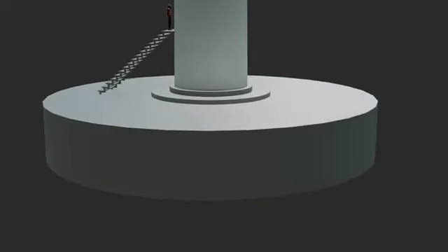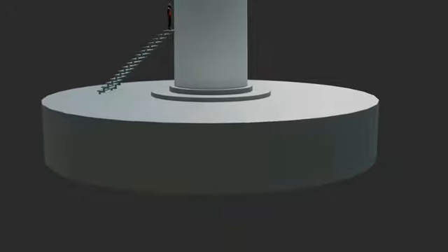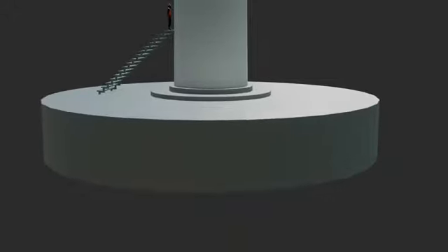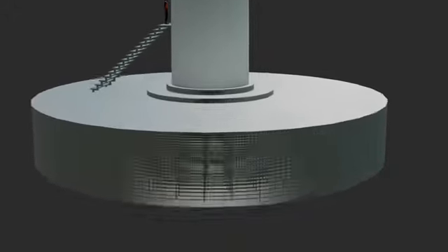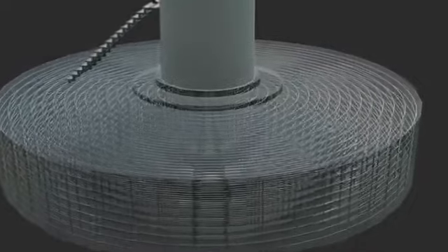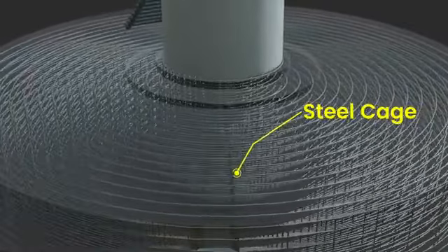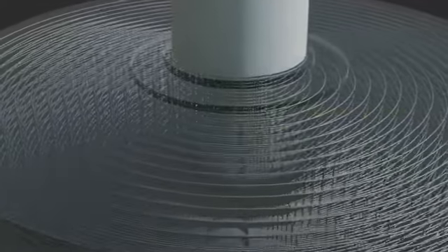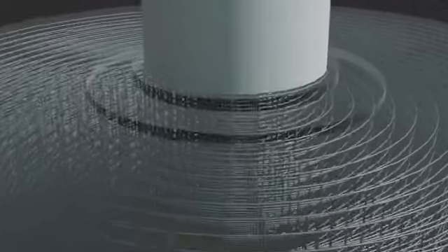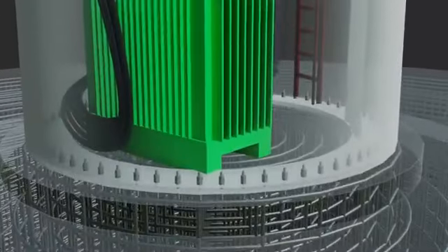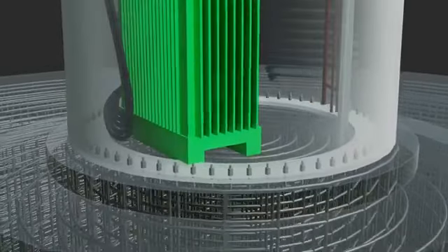A typical gravity foundation for a 2-megawatt wind turbine is approximately 15 to 20 meters in diameter and 2 to 3 meters deep. The foundation contains a precisely engineered steel anchor cage, a complex assembly of reinforcing bars, set into the center before concrete is poured. This anchor cage contains the large anchor bolts that connect the foundation to the base of the tower.